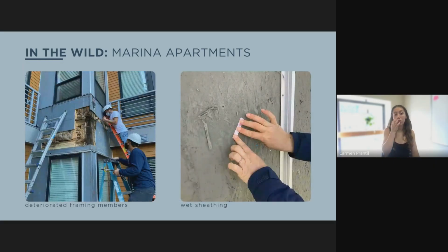So we began to open up the exterior wall assembly, and this is what we were seeing. Apologies if anybody is eating while watching me present this today. It's not exactly the most appetizing to see on your screen. So essentially what we found here was, number one, they had poly installed at the interior. So this is going to act as an interior vapor barrier, and again, it's going to reduce the drying potential. It also is going to delay the signs that they saw in the interior. So again, they weren't seeing things on the inside like warped floorboards. They weren't seeing things like bubbling paint, peeling interior finishes. They were just getting sick.